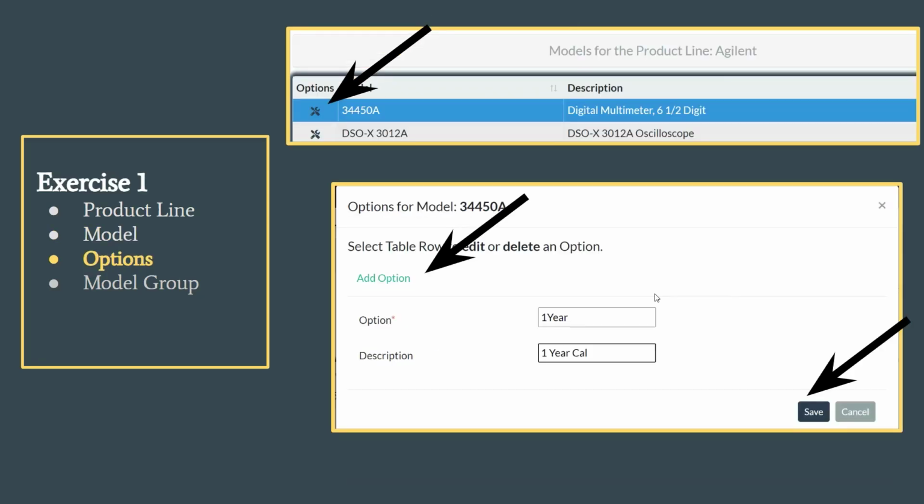So then underneath the model, we're going to come in and click the options button. And this is going to expand out. And what we came up with in Metrology.net that we think is good practice is putting in the cal intervals, so that now when you load in a meter, the user can put the cal interval that meter is calibrated at. And the way we built this is we built it to where the 1 year cal interval is the default, but you could set it to a 90-day cal, a 1 year cal, or other types of things to choose your test points when they come.